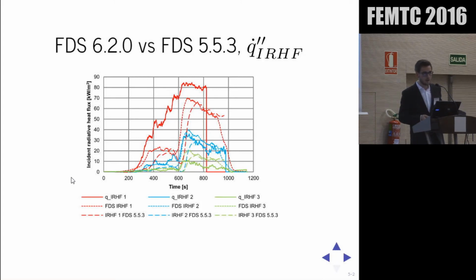After they used the beta version of FDS 6, they saw that the plume all of a sudden ejected closer to the facade, corresponded better with the measurements, and the actual photos looked better. Given this, the main reason for the higher output data for FDS 620 compared to FDS 553 here may be the change of model for turbulent viscosity. That may have affected the velocity field through the opening, hence also the appearance of the ejecting plume, and then the impact on the facade.